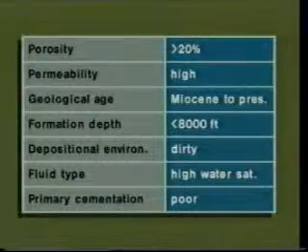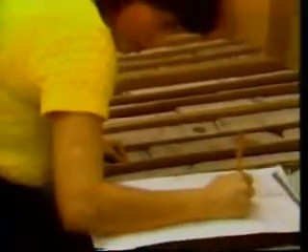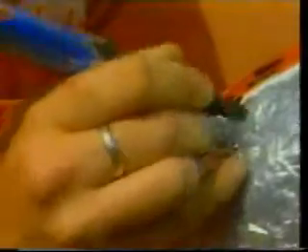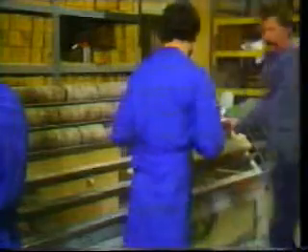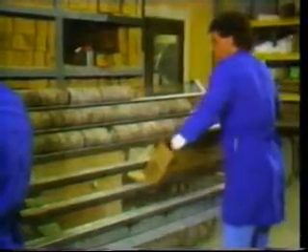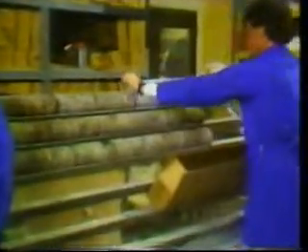Let's look at another analysis method, one that relies on core samples recovered from the subject well to give an indication of potential problems. Obviously, if the recovered core falls apart as it is retrieved, or the sand grains can be rubbed off or broken, the chances of sand production would be great. Care must be exercised during coring operations to employ techniques that ensure the recovery of good samples. You may wish to review the special coring and core handling techniques presented in PE 405, Core Analysis, and GL 303, Sample and Core Handling and Analysis.